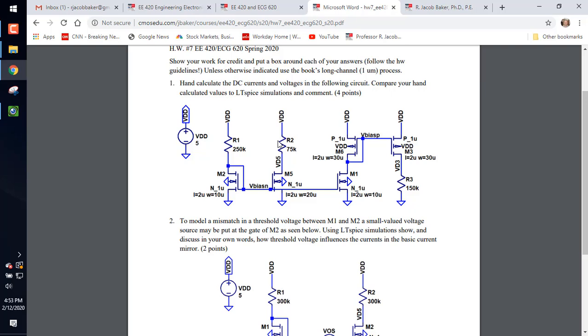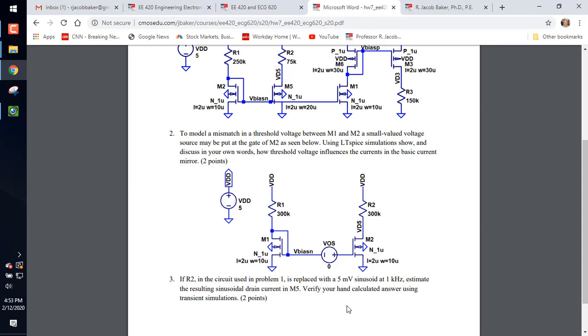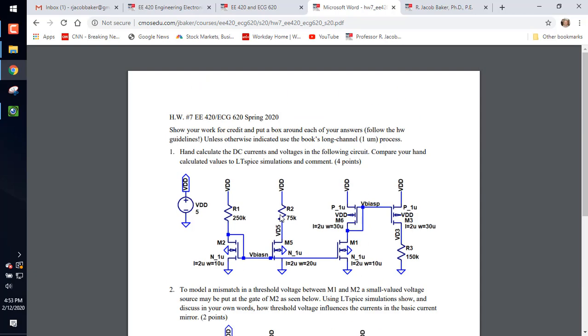If I ask now, if this is an AC of 5 millivolts, what's the AC current flowing? It's going to be this 5 millivolts divided by the output resistance of the transistor, R out, which you calculate is 1 over lambda ID, where the ID is the DC current that you have flowing here.